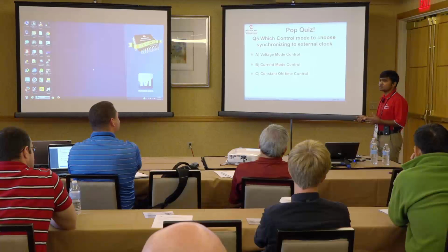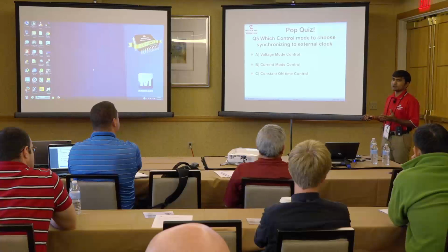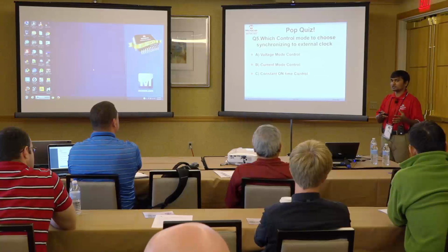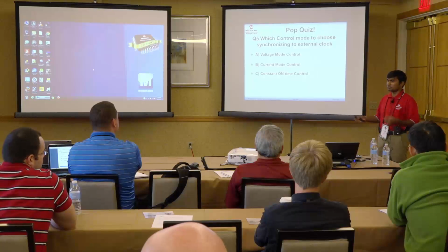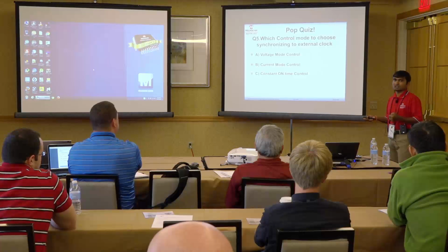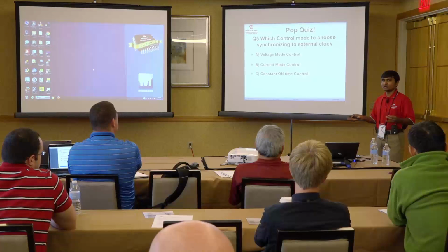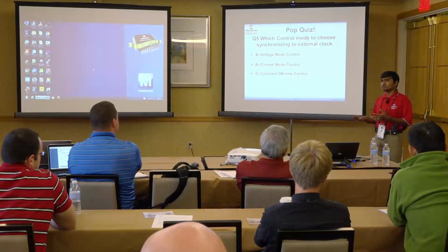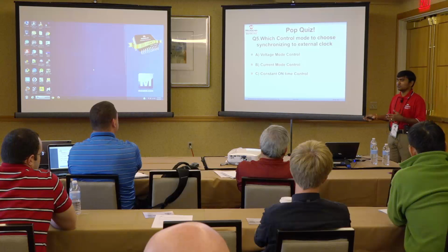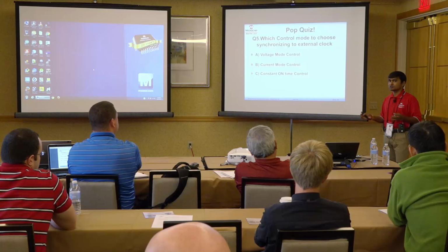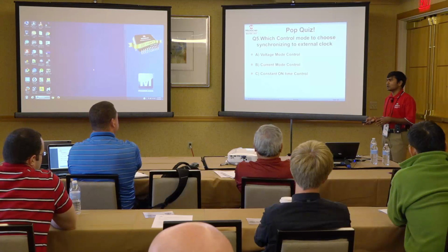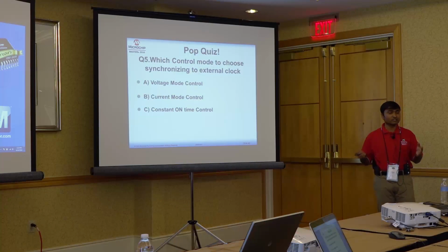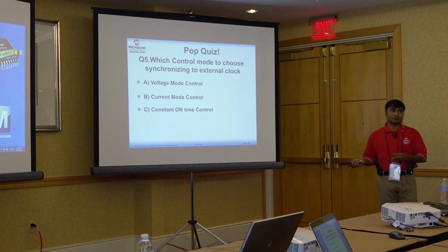In voltage mode control and current mode control, there is a clock. That is the reference clock, so you can synchronize to the external clock. But when it comes to constant on time, there is no clock in the system, so it is difficult to synchronize to an external clock. That problem has not been solved for the COT unless we use another PLL in the loop, which complicates the design. As of now we do not have any products where we can synchronize an external clock to the COT controller.